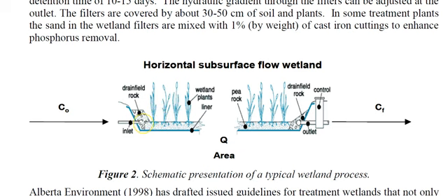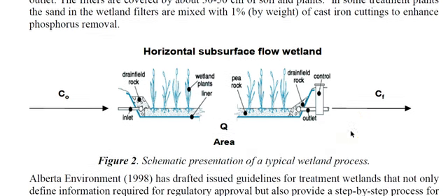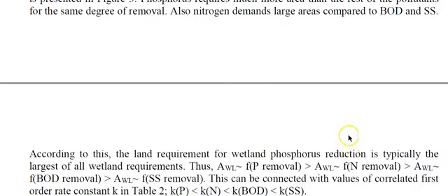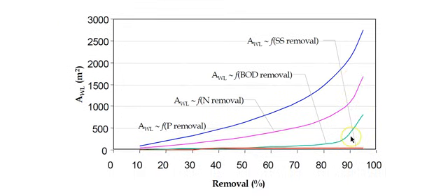But as long as you let the water from the advanced treatment upstream go below the surface in the root zone of plants, you avoid that problem. And by the time you get to the outlet, very little pathogens left. Still, there can be some though, so it's not like you can just dump it anywhere, but infiltration into the ground is certainly the safest in terms of that. All right, so let's scroll on a little bit.